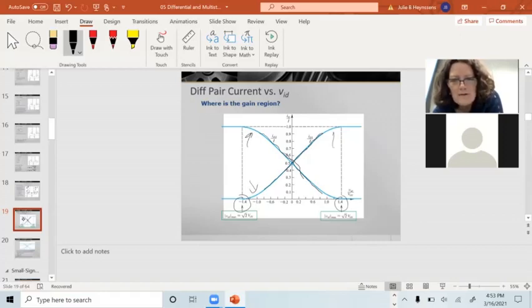If you get too close to the absolute maximum limits on these transistors, they stop behaving well. You'll start to see gain distortion. You'll start to see the gain rolling off. You'll have really low gain. You don't want to operate a circuit close to its power supply limits. Now this gets to be a problem.